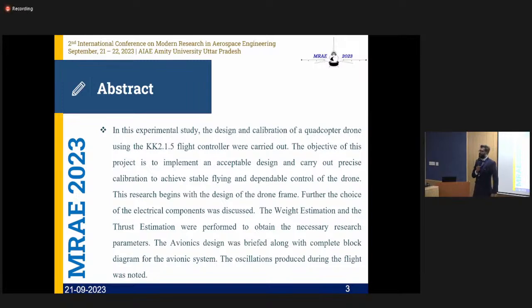So unless you know the exact weight, include every single nut and bolt in this, because we are playing with just a 2 kg, 3 kg payload, something like that. So even some nut and bolt should be considered. It is not some big aircraft, right? So every gram counts. That's why we need to do the exact weight estimation, as well as the thrust estimation, with accuracy. Right?